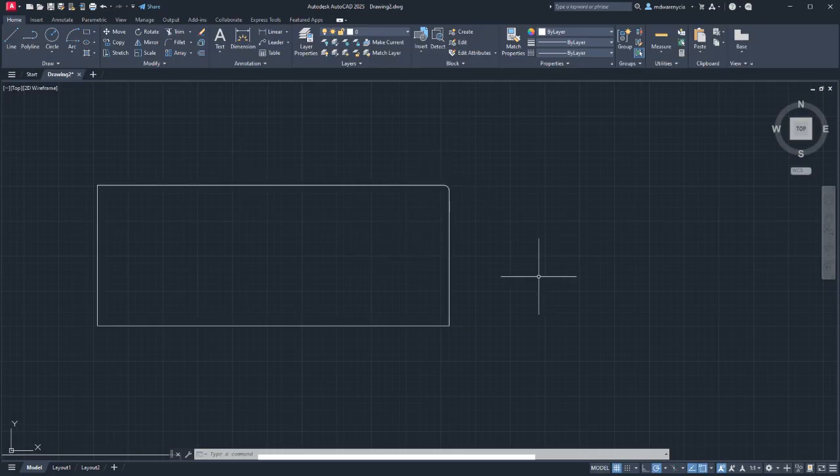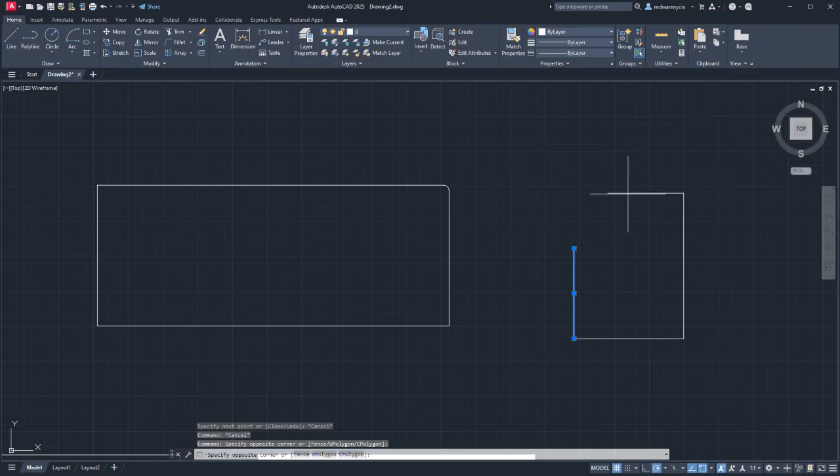If it's a couch, I could fillet the edges of a couch. It goes on and on, so there's a bunch of uses for the fillet tool. Another one is if I have been doing some work and I have something going on where I have this opening right here, radius 0. In the past, I've used this to close up weird gaps. So if you use those with a 0, that can actually save you some time.